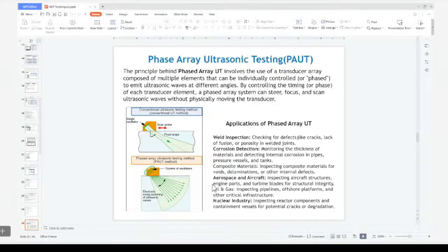That defect either traps the heat and cools the region, or emits the heat and makes the region hotter. So it will be either a colder region or a hotter region. So when I have a standardized thermogram and your new part thermogram, you just map it, and you will understand. Wherever I get this disturbance of temperature, the temperature difference regions will help me identify the defect regions, like whether it's a crack or voids or any corrosion.